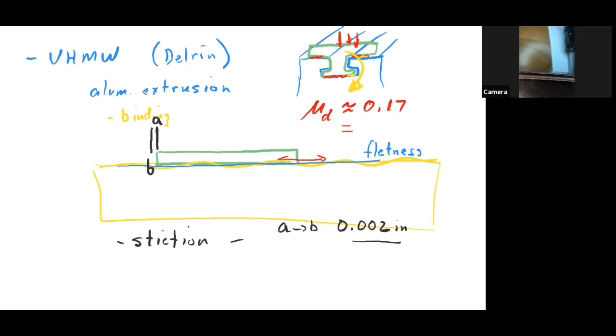Okay, so there's my motion. I'm going to try and make this move. I can't make it move less than 1/16 of an inch. When you have a large differential between the static and dynamic friction, you can't do 0.02 of an inch with that push, or you have to wrap other controls around it.